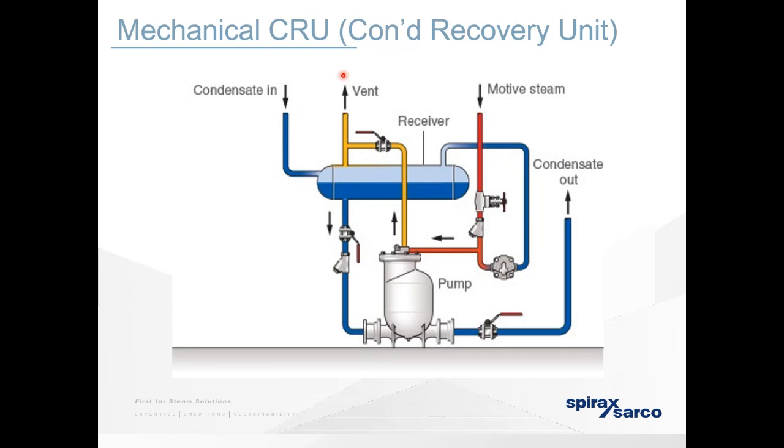It depends on the accuracy level you'd want. The very basic would be the steam out, the condensate in. But if you really want to be truly accurate, you would then add to the services. You could add a meter to the makeup water, and to the fuel that the boiler's using, so you can see how much bang for your buck you're getting, which would give you the efficiency of the boiler. And then any losses, any dump to drain that you're doing. So it depends which level you talk about. At minimum, you would need 2 meters.